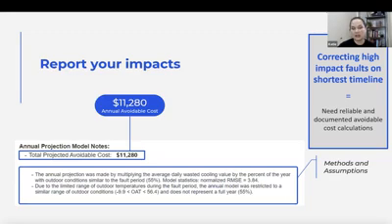Because in reality, would this campus have allowed this leak to happen for an entire year? Probably not, right? And actually, this calculation doesn't look at the full year. It's assuming that it's only during the outdoor air conditions where this problem would happen. And then it also says we think it probably would only happen for half the year, 55% of the time or something. But if you still thought that's a bit much, I think we'd find it in a month. You have enough information at your fingertips to say, okay, instead of multiplying it by 5 months, I'm going to multiply it by 3 or whatever the number is, and you can knock that number down when you're reporting.